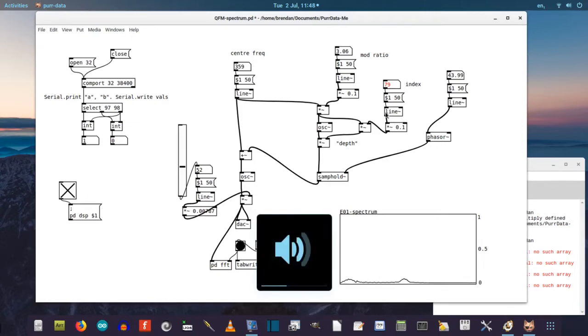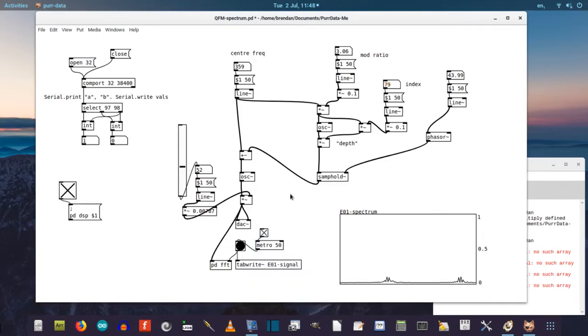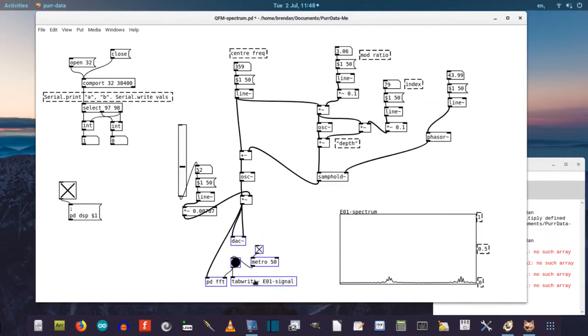That's nice. And a little proviso in FM synthesis, and particularly chaotic FM synthesis, is that our final output doesn't do any harm. In fact, it's a safety measure to include a low-pass filter around about 2 kilohertz. And that value will change depending on age and listening environment, how sensitive your ears are.